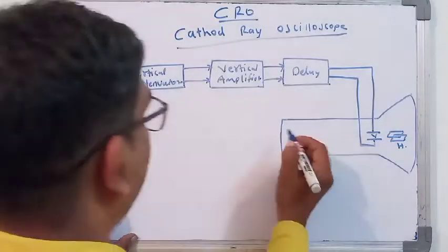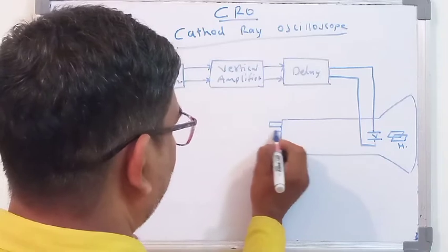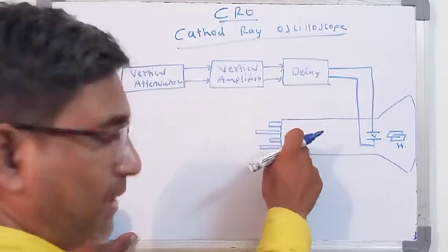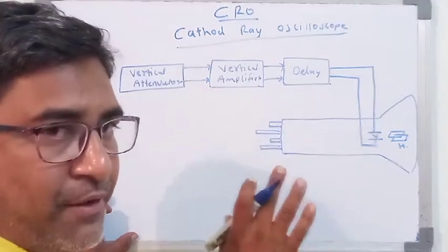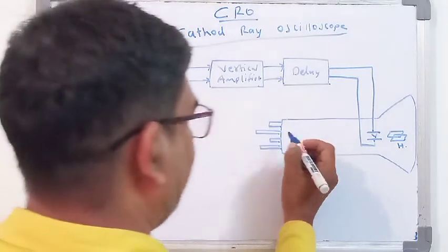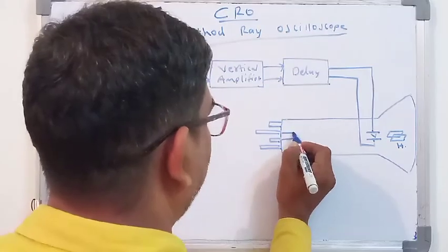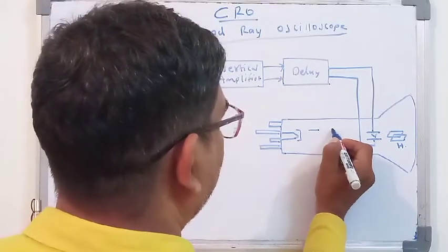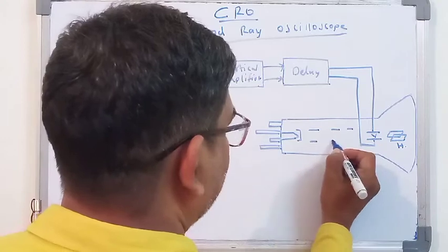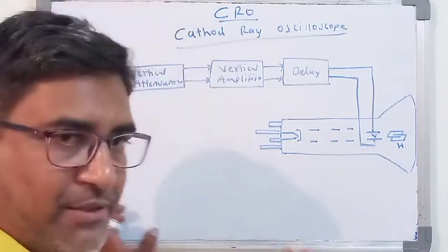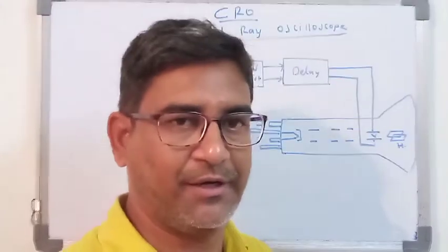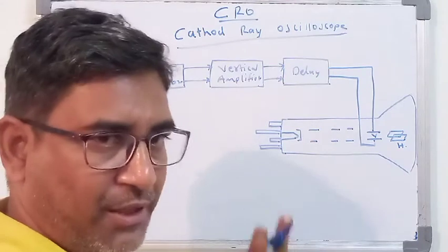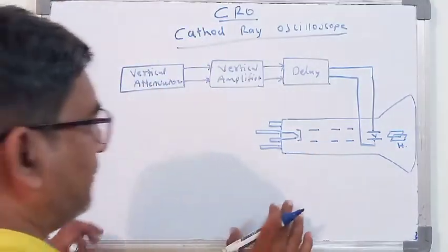Okay, in this CRT there are different pins, shown like this. Inside this CRT there is a control grid. The filament is also present. So the filament and the control grid are indicated like this. And here are the different anodes: the pre-accelerating anode, focusing anode, and accelerating anode, indicated here in this CRT.